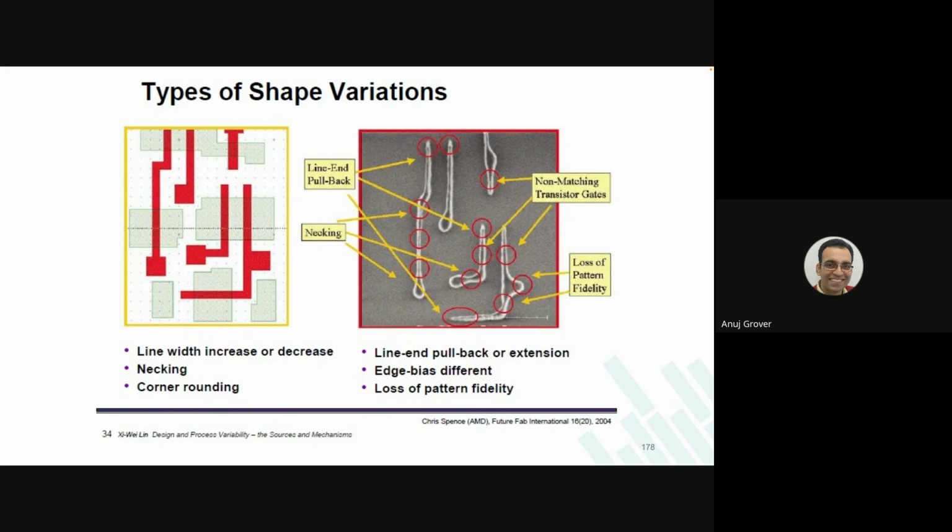If the impact is significant, then only for the memory array, the optical proximity corrections and resolution enhancement techniques are tweaked additionally so that we get the desired yield. Because it's a systematic variation, you can run a Monte Carlo simulation and do something about it.